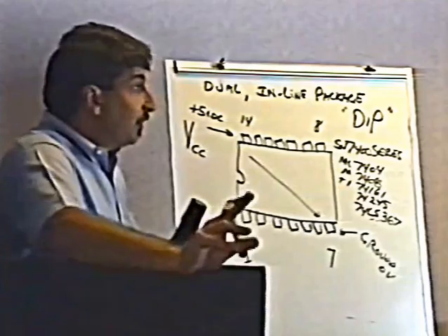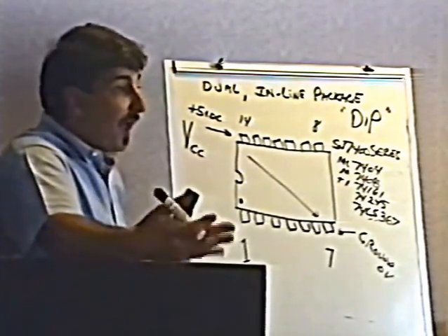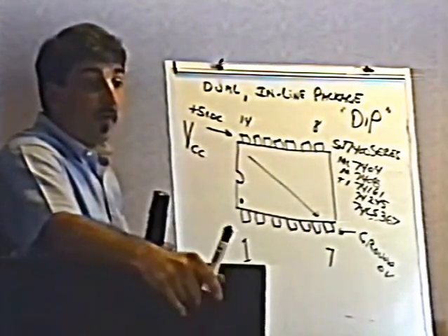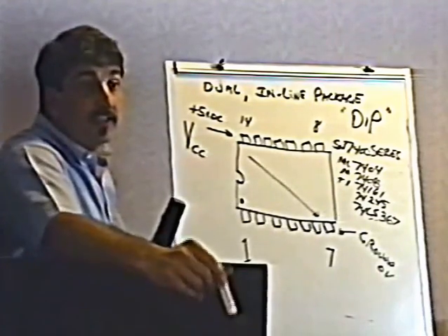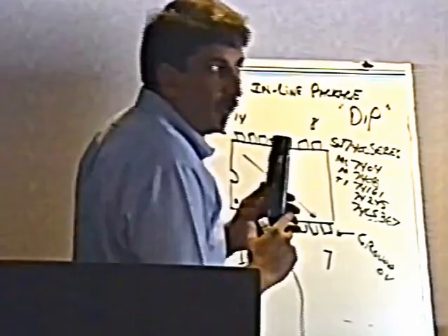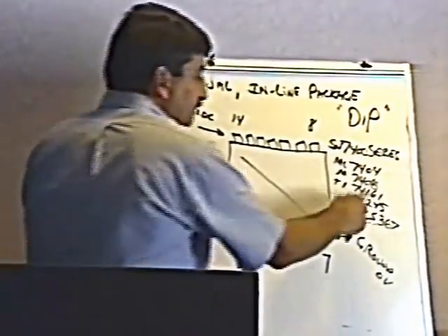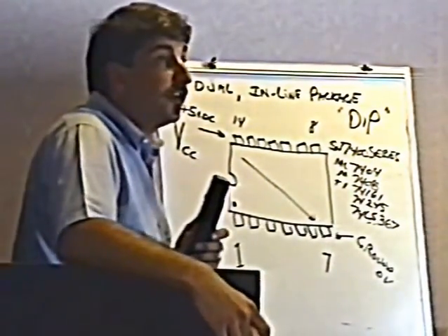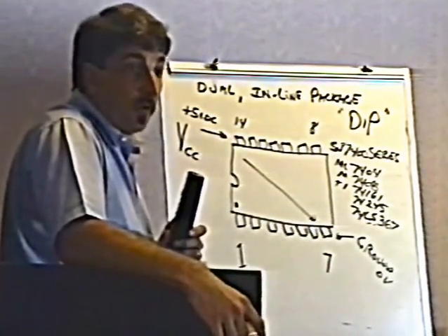Whenever you see a two-letter prefix on an integrated circuit, you can ignore that. That has nothing to do with the part number. That will change depending on who makes the chip, whether it's made by Texas Instruments or Signetics or Motorola or anybody. What we're looking for is the first two numbers. And if it's a 7400 series, those are the ones I'm looking for.